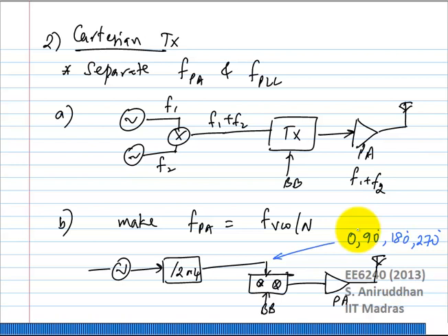Now what you need to worry about? You need to worry about the second harmonic or the fourth harmonic of the PA pulling the PLL. Remember that the PA is actually outputting a lot of power, and let's say the PA is outputting 30 dBm. The second harmonic may be 20-25 dB below. So it is still significant. It's not very large, but let us say if it's 20 dB below, you are still outputting a second harmonic content of plus 10 dBm. Okay, so how much is that? 10 milliwatts. That is still significant enough to pull the VCO, but by very little. You are probably not going to affect it too much.